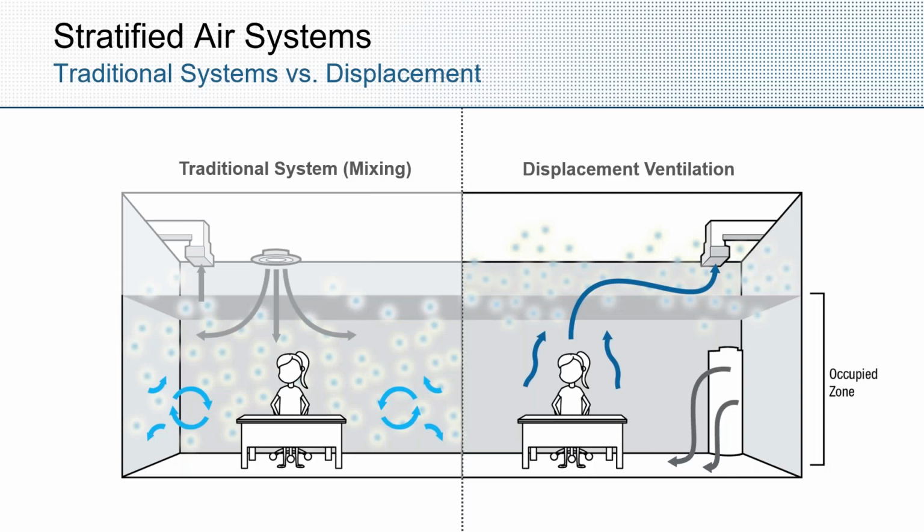All right, so again, first off, just comparing to an approach that Ryan was talking about. The idea here is actually we're not dealing in worlds of really throw anymore. So we're going to try to really test you today and get you to think about a different approach as well. Looking more at a buoyancy-driven, naturally convected space. So in this scenario on the right, where you're looking at displacement ventilation, we're going to let the air fall into the space that is around 10 degrees cooler than the set point in the space.